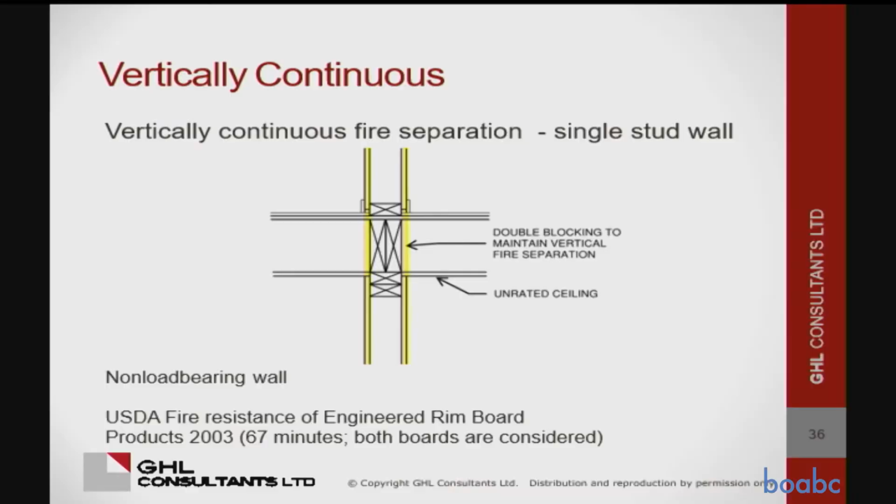And then in a non-load-bearing wall, you don't have to add all that double extra fire blocking, because the rim boards are just the fire blocking. They're not structural members. They're just maintaining that fire separation vertically.